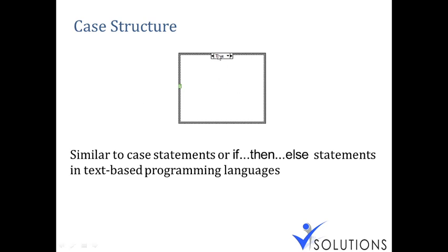Rather, you have a label called true, and you have a question mark terminal. It is called a case selector terminal. I repeat, this is called a case selector terminal, which makes the decision. This is a very important terminal here. He makes a decision, so he will be deciding which function to execute or which certain code to execute.